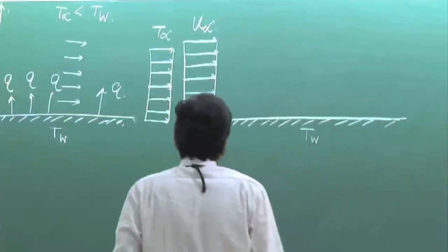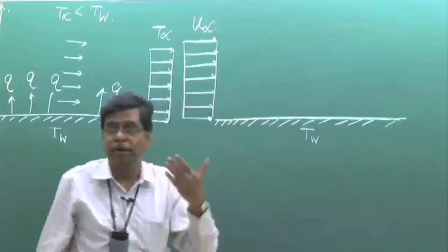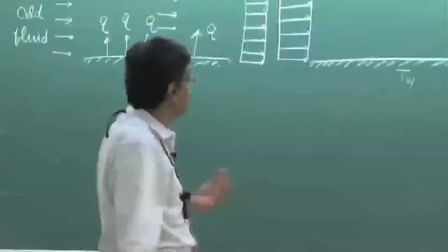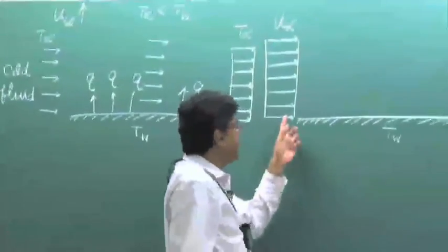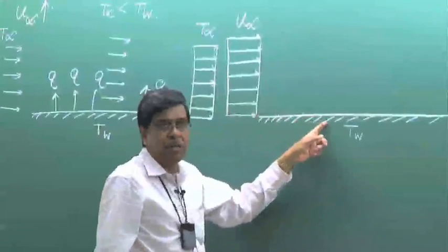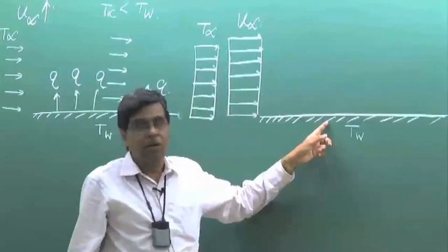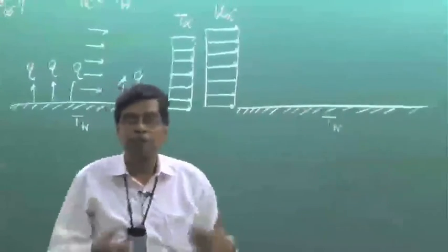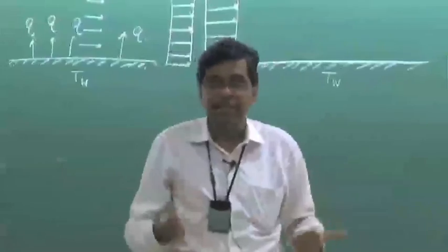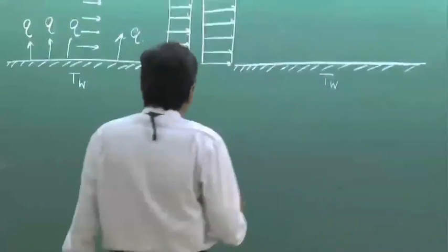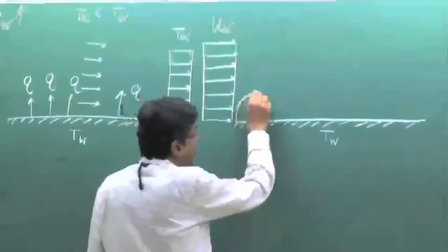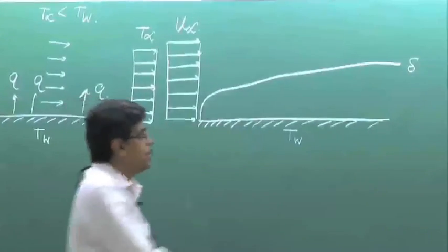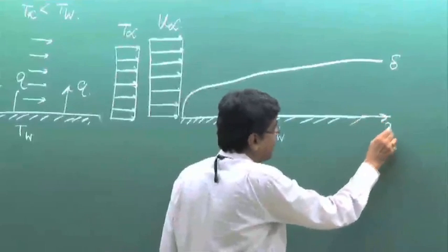Now as we know from fluid mechanics, which will be told again in detail afterwards when we have a recapitulation of the basic fluid mechanics, the interaction between the fluid and the solid surface, and in consequence the momentum transport in the fluid because of its properties like viscosity and density, leads to the development of a layer known as the boundary layer, which is a function of this distance, if we consider this as x.